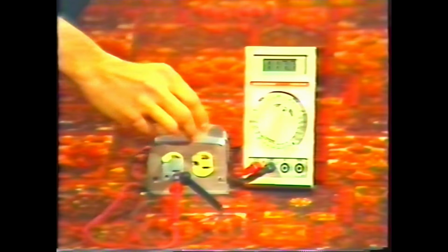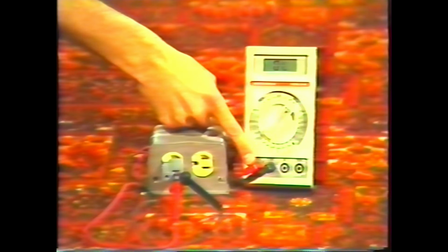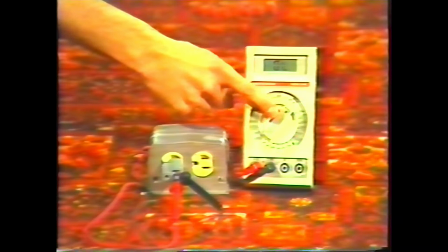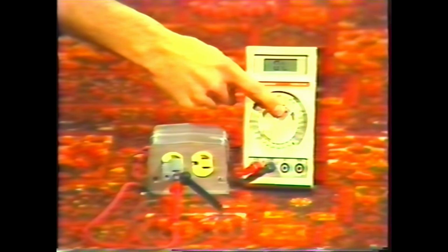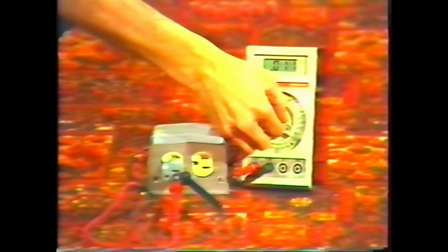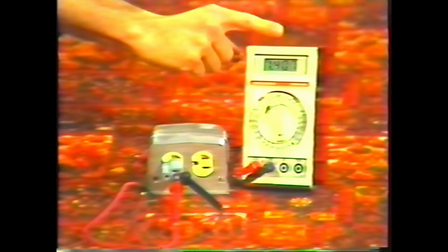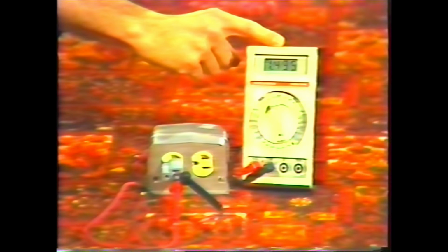If I were to accidentally set the meter too low, say on the 20 volt range, the meter reads OL. Well, OL stands for overload, but that doesn't mean that I'm hurting the meter in any way at all. It simply means that the input voltage coming into the meter through the red and black leads here is higher than the setting here on the selector knob. In fact, I can actually rotate the selector knob through all of the ranges, including the resistance range, without fear of damaging the meter. The meter is fully protected or idiot-proofed against all kinds of accidental high voltage overloads.